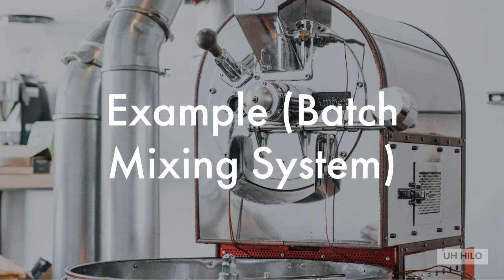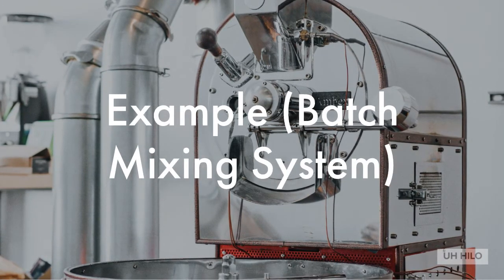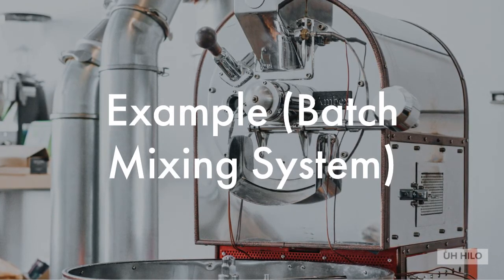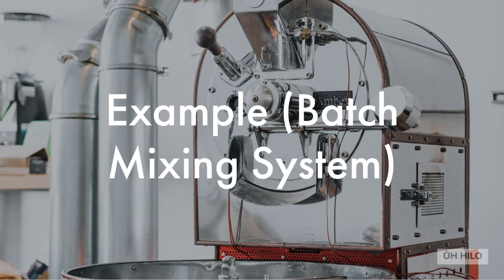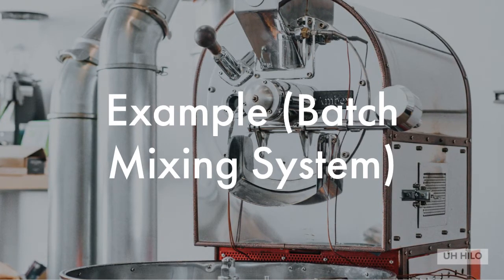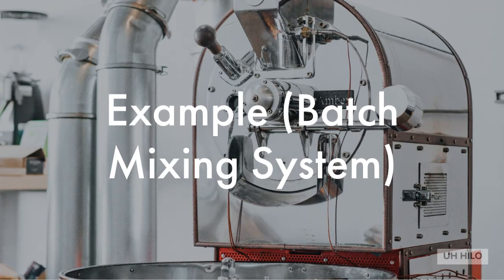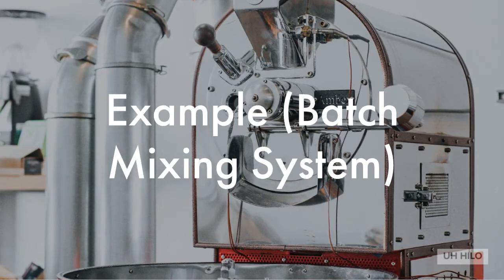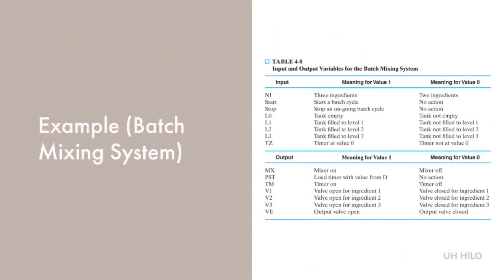The mixing system has a button for starting the operation and a second button for stopping the operation at any time. There's a timer for timing the mixing cycle. A manually operated dial that provides a starting value to the timer specifies the length of the mixing cycle. The timer counts downward to 0 to time the mixing. After mixing, the output valve is opened to remove the mixed liquid from the tank. The inputs and outputs for the sequential circuit are given in this table.